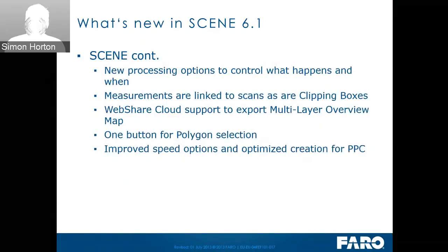We've also made some modifications to allow you to control what actually happens with processing. Prior to 6.1, when we released 6, as soon as you process the data, that would effectively save and apply filters. It would then create a scan point cloud and it would colorize it. This went against workflows that some users like to use of old. So now what we've done is allowed you to control what you need to do, even down to the point that you can now load and unload scans in the new interface as well.